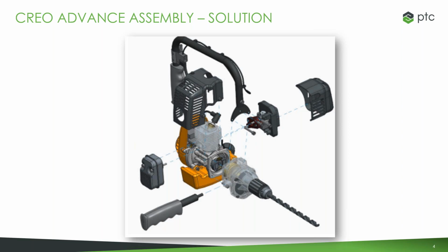Top-down design is an incredibly useful methodology to use because it allows for more control over references, more control over what's happening. You can have that concurrent design process because everybody knows what's going on right at the start of the project. You don't have to have anybody waiting for anyone. Everything fits together at the end. And most importantly, you have flexibility at the end. So you can have these really large assemblies, have people working all over the place at the same time. It fits together perfectly, and it's incredibly flexible because you can manage the references. So top-down design is a great option. So if you're not familiar with it, this is definitely a good introduction.